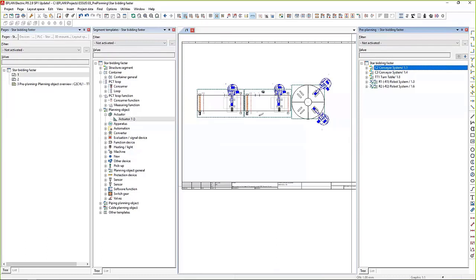So if you use other tools like maybe AutoCAD Electrical or even SolidWorks Electrical, the challenge there is, again, the bottleneck is the underlying tool. These are two mechanical systems that are used as a starting point to do electrical. If you look at AutoCAD Electrical, for example, you will see that it's AutoCAD with a whole bunch of scripts and add-ons on top of it, which make the whole system very fragile in the sense of, what if I add a block which is not AutoCAD Electrical in there, and then you can break the system. So there's a certain amount of fragility in there, and you have to be very meticulous and structured to be able to stay there. EPLAN is not that at all.